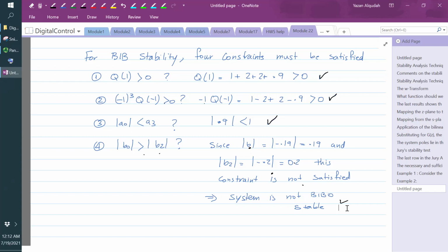So if I wanted to use Routh-Hurwitz, one thing we can do is to transform what's inside the unit circle so that it is the left half plane of a space that we call W. If we do that transformation, then I can apply Routh-Hurwitz to that W space.